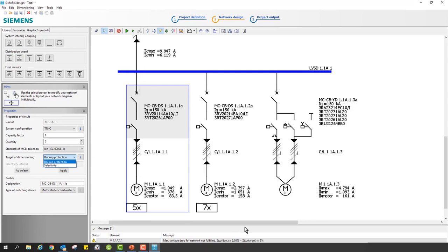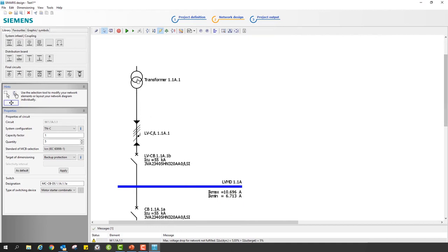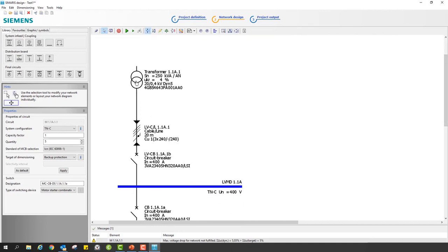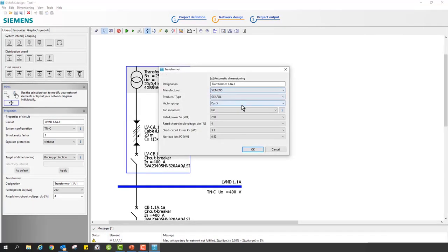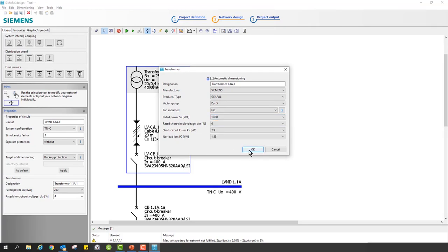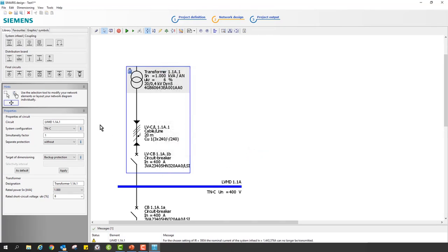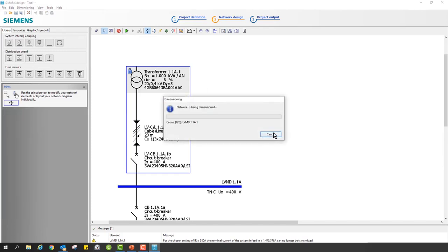When talking about control panels, it depends, because when you disconnect a motor in a machine, you often will like to disconnect everything. So here, selectivity won't be that important. Here, you will sometimes go for backup protection, making your solution more attractive to your customer. Then again, you will have to discuss with him whether he wants backup or selectivity. So remember, every time with a backup dimensioning, you will have a cost advantage.